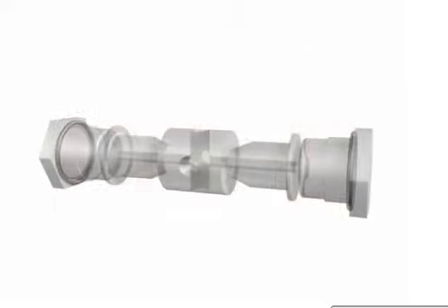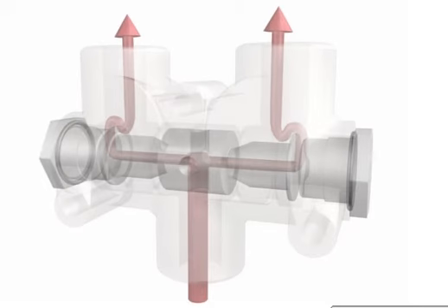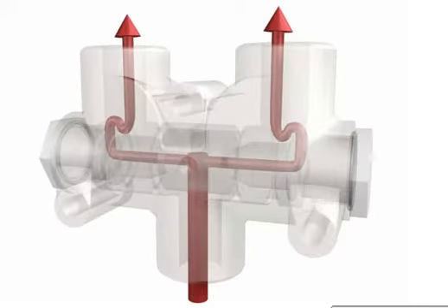Inside the housing is a sliding spool with cross-drilled holes in the center and through the entire length of the spool. The spool is able to move freely in the housing. Flow from the inlet enters the center of the spool through the cross-drilled hole. The flow divides and flows to both ends of the spool. Fluid flows out both ends of the spool, around the ends of the spool, and out the narrow passages to the outlet ports.